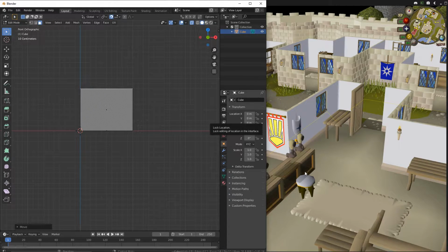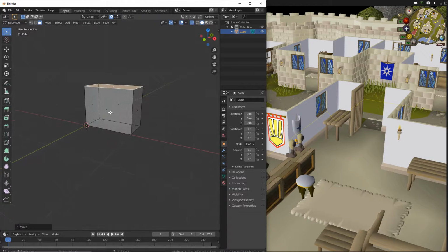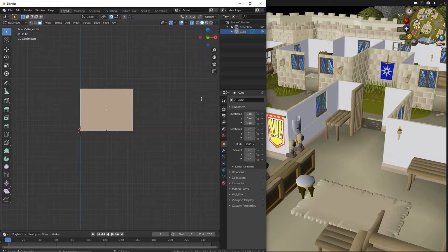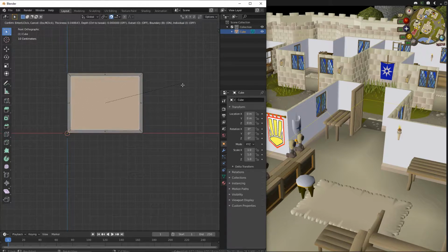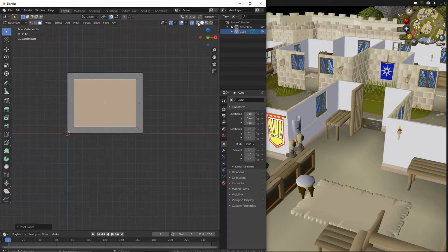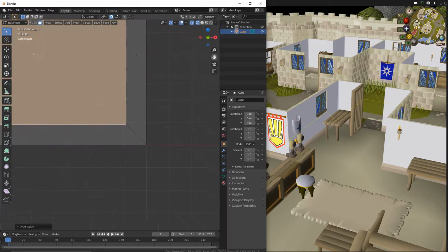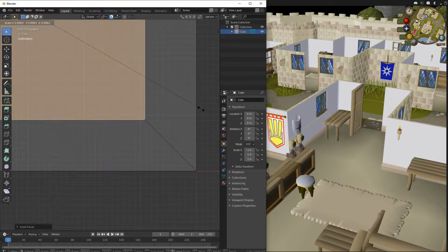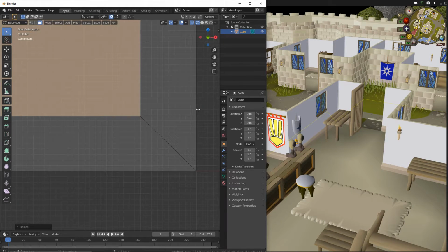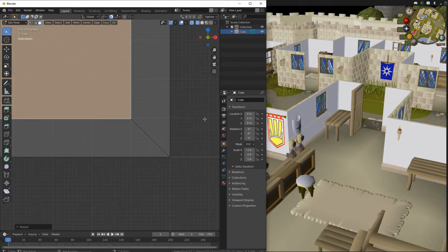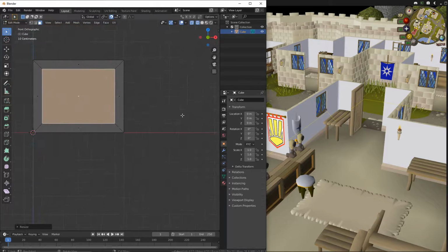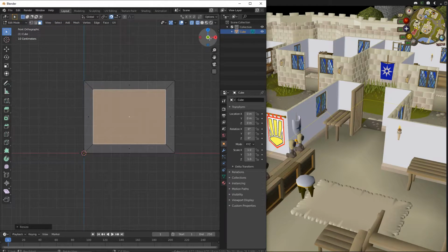We then need to inset the face that's on the front of the bar here. So to do that, we'll select the front face, press I to inset. Again, I'm going to jump into the Y view here so I can see how much I'm insetting it by. And I want to just inset it by about another 10 centimeters there. So to get a clearer view, we can turn on the wireframe mode, zoom in a wee bit, and we can see that it's still a bit too large there. And we'll just scale on the Z axis a bit as well. There we go.